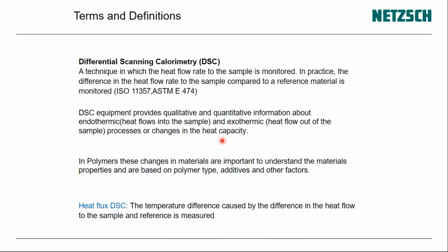The NETZSCH DSC is based upon the heat flux DSC. Now, as I mentioned to you, the definition is the same. The temperature difference caused by the difference in the heat flow to the sample and the reference is measured. There is also one more method, which is called the power compensation technique. In a heat flux DSC, what we are showing here, we have only one furnace,